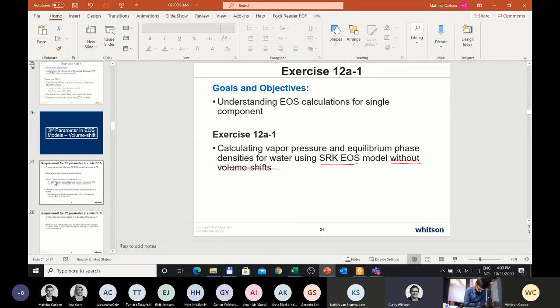The other would be to use laboratory data, CCE data in the single phase region up to initial pressure, and to create synthetically or manually the Bo or the Bg pressure dependence that honors the laboratory measurements of compressibility, which would be correct. So it would be a manually created black oil table.